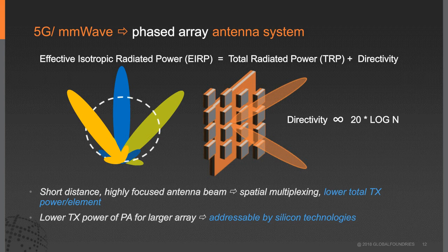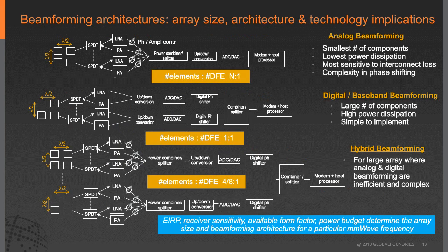So you need phase shifters to compensate for this electrical path difference by adding a variable phase to each path, so that signals from a desired beam direction add constructively while signals from other directions cancel. This is known as beamforming. Now let's talk about the different types of beamforming. There are three different types of beamforming architectures: analog beamforming, digital beamforming, and hybrid beamforming.